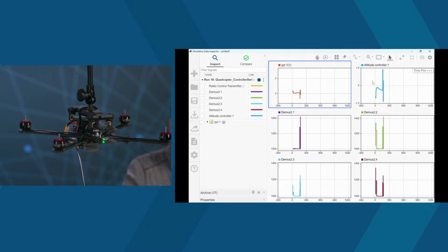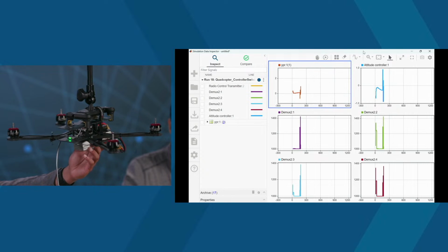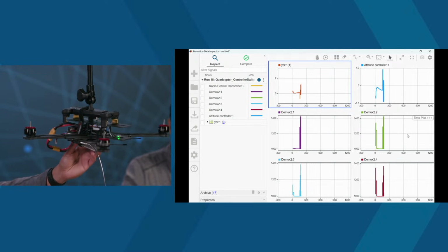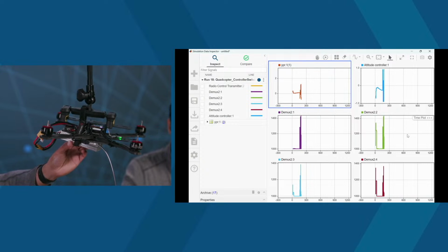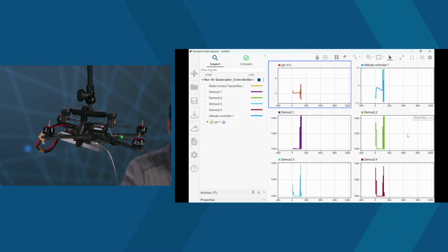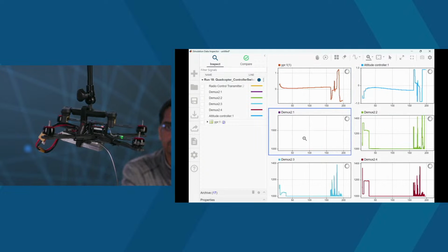So now the flight controller is running. I'm going to showcase the yaw control. If yaw goes to one side, I have 2 of the motors shooting up, whereas if yaw goes to the other side, I have 2 of the other motors. That is enabled with one of my switches. So I'm going to enable the switch, and I'm also going to zoom into this with a time zoom so you can see what I'm actually showcasing.